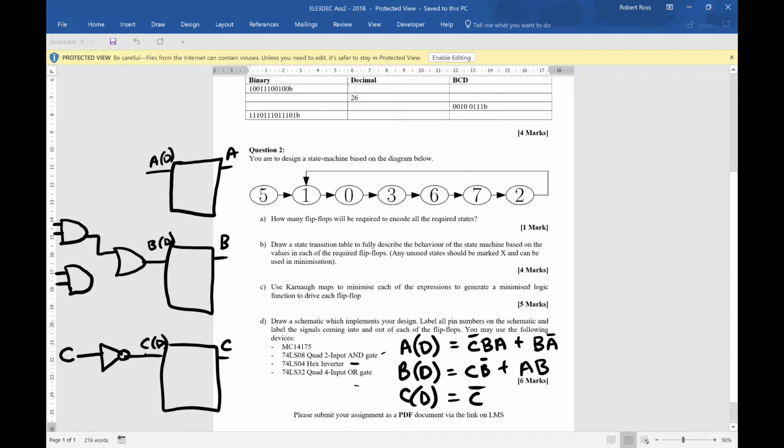So in that case, if we've got 4 inputs, we can't just leave the other 2 floating. We need to do something with them. So we'll tie them to ground. Okay. If we're doing it with AND gates, we'd need to tie them to a high voltage so that we could actually get an AND output. With OR gates, we need to tie any unused ones to ground because we're not using them. Okay.